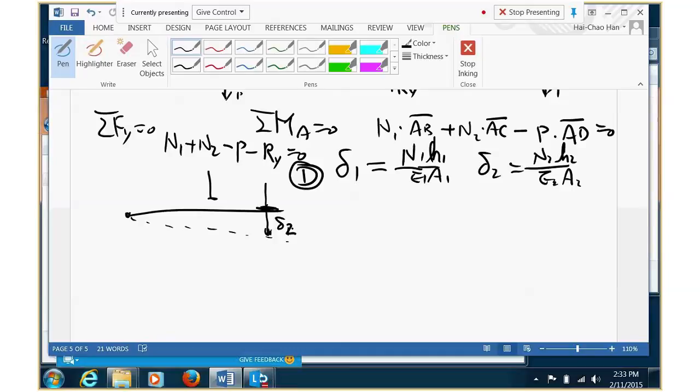What's delta 1? Okay, when you write this equation, what does delta 1 mean? It's the elongation of bar 1, right? Elongation of that bar. Okay, this bar originally ended here. Now, how much does it elongate? It must move to here to meet this rigid beam to move there, right? So therefore, this is the delta 1. What I'm drawing here is delta 1. So this part is delta 1, right? Now, where is the capital delta, the defect? It's this part, right?